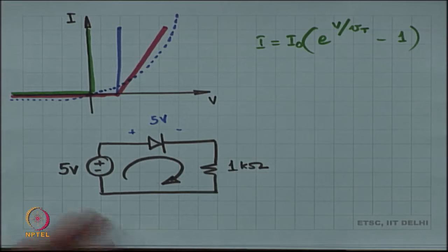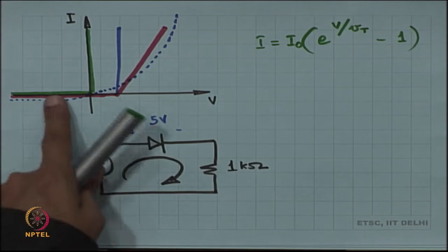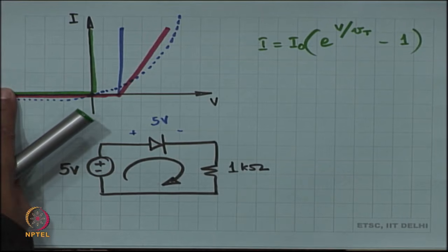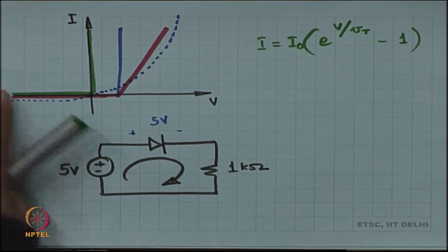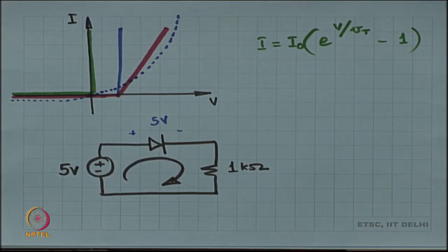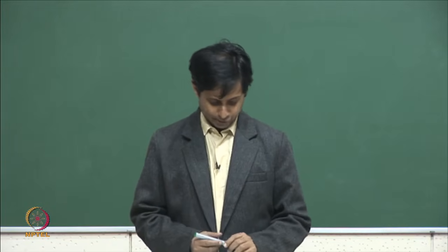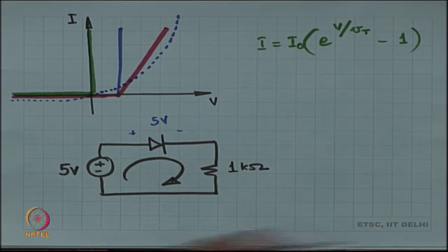We have to be in the negative axis if no current flows through it. It can be any drop as long as it is negative, but this is a positive drop, which means that our assumption is not true. So, therefore, the diode has got to be on, not off.